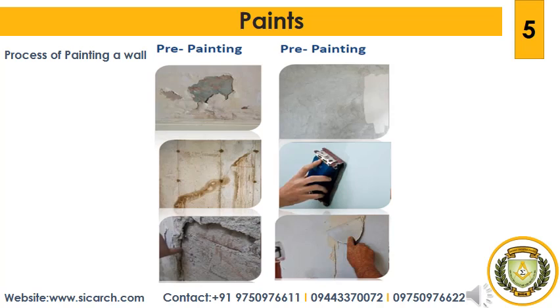For the first coat, red lead ground in water and mixed with strong glue size is used in hot condition. This coat dries in about 10 minutes and then the second coat is applied. The second coat consists of red lead ground in oil and it is thinned by boiled oil and turpentine.